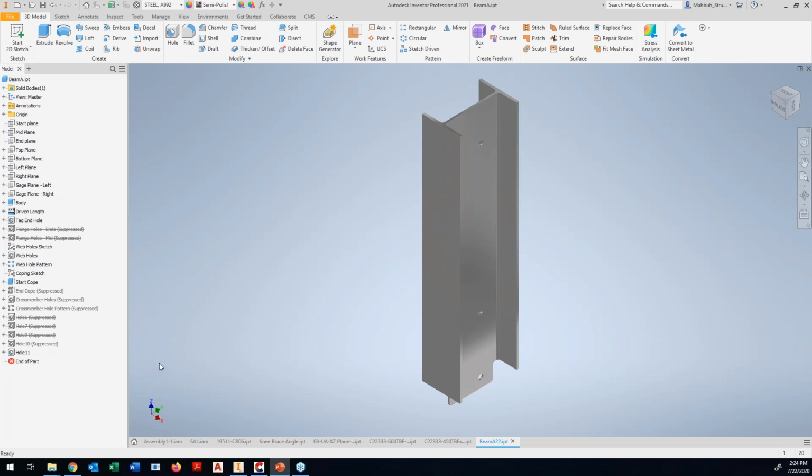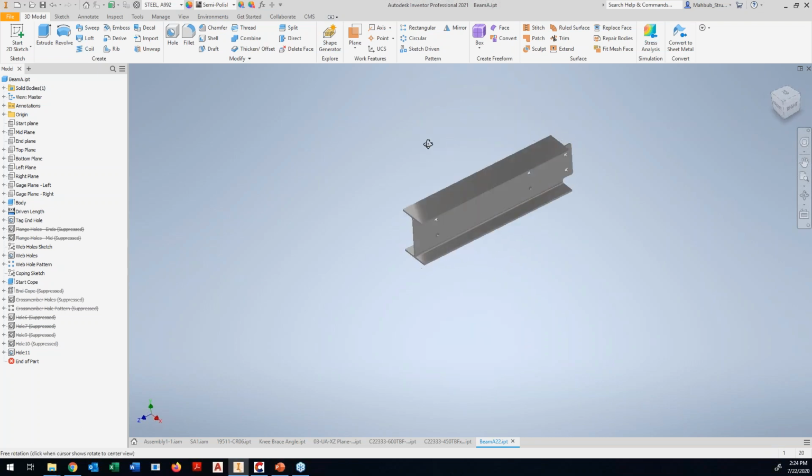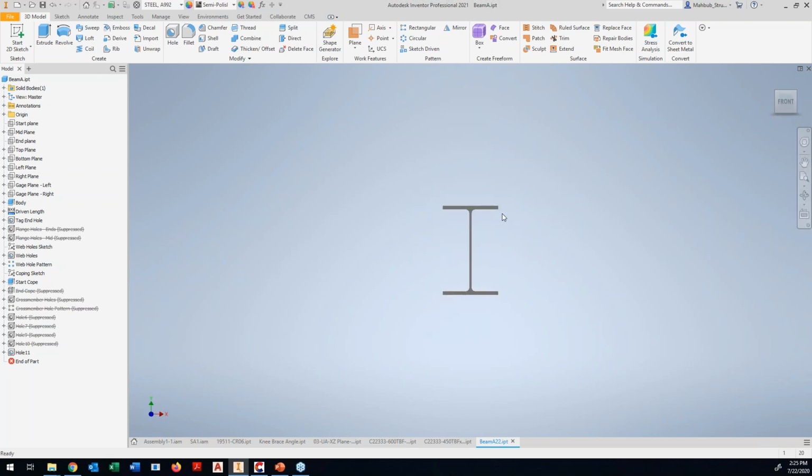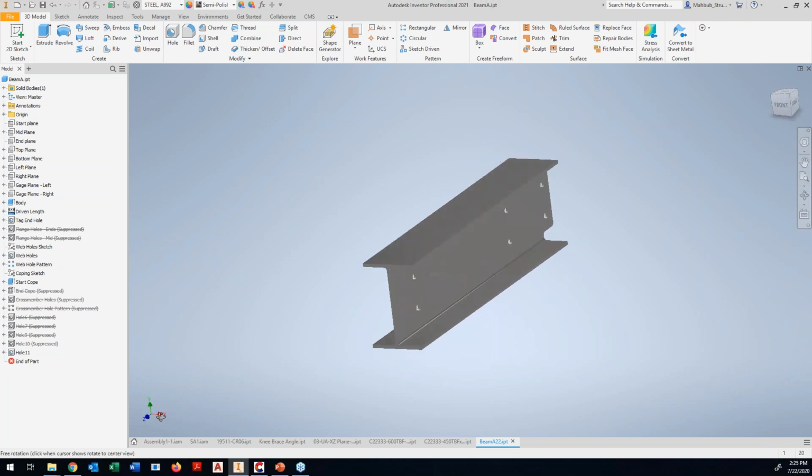Okay. So the first thing that I'll be showing you is how things work on the part level, right? By the way, if your part is designed as a Frame Generator model, these are all supported, okay? And if you have a derived part as well, this is supported as well, okay? So let's work on this simple side beam here. As you see, if I just bring it over here, this has been created from Content Center. So as you see right away, if I just go to my front face, it's on the XY plane, and the Z is definitely coming out of my screen, the direction, the plus Z. So this is exactly what we look for.